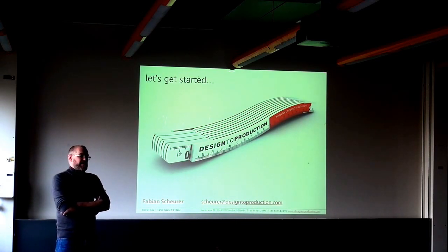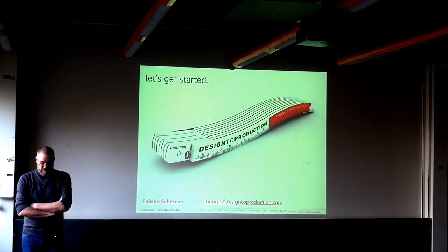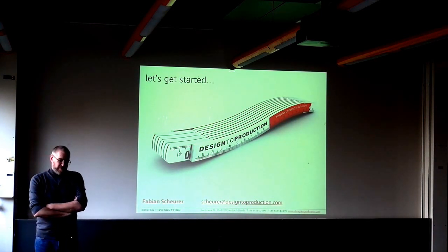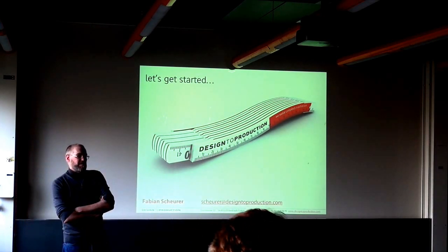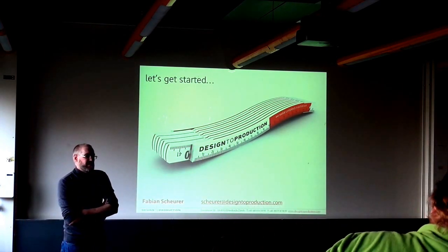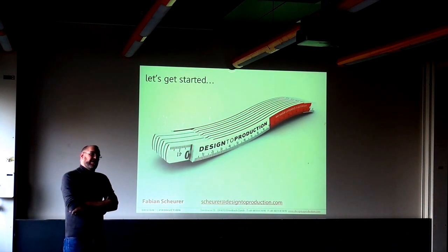I mean, additive manufacturing is always a question of scale and resolution. As soon as you start using bricks as your additive building material, you're getting reasonable sizes and reasonable building times. So I think it was a smart move of Gramazio and Kohler to use their robot for stacking bricks on top of each other. But it gives you a resolution of roughly 10 centimeters that you can work with.